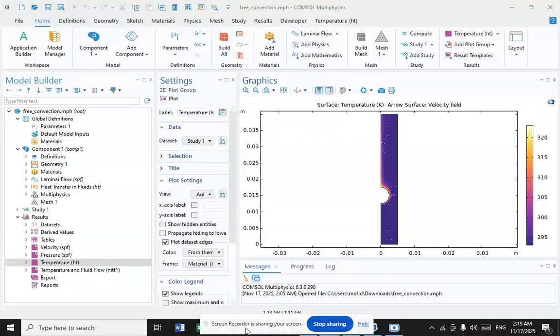If density variation delta rho is caused by a spatial non-uniformity of the temperature field, then a flow arising in the Earth's gravitational field is called thermal gravitational convection. The density variability may also result from a non-uniform distribution of concentration of any component in a mixture, or from chemical reactions, differences in phase densities, or from surface tension forces at the phase interface. In this case, concentration diffusion or convection is implied.